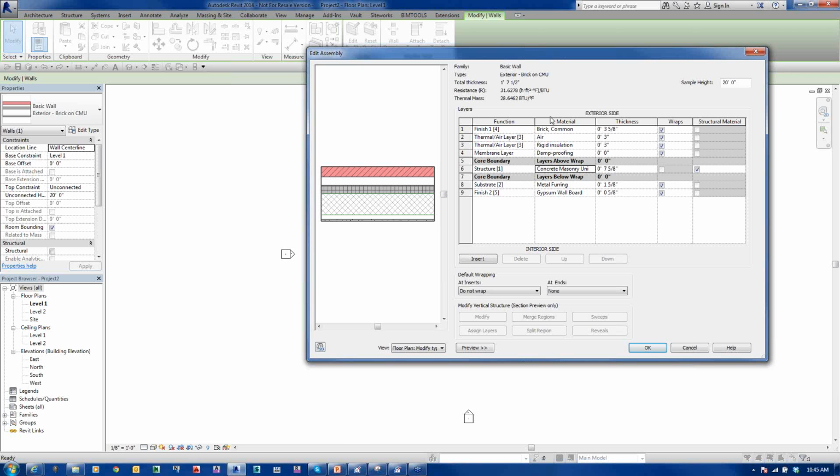Yeah, potentially. It seems like Chris had a question on there. It says, so if I create a set of materials on the walls, is there some place where the comprehensive wall R value is listed, or is this manual? Oh, it says, never mind, just saw it. So yeah, it is calculated for you if you're using Revit 13 or 14. Those R values, or U values, or thermal mass values, I should say, are coming over, and you can plug those in.